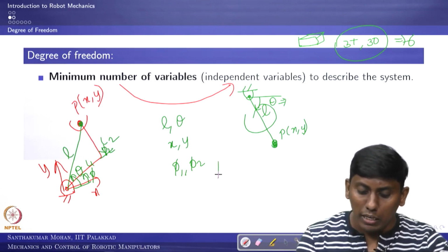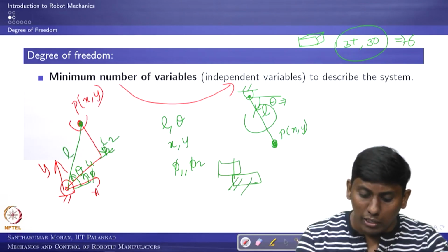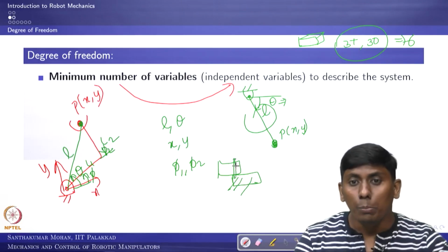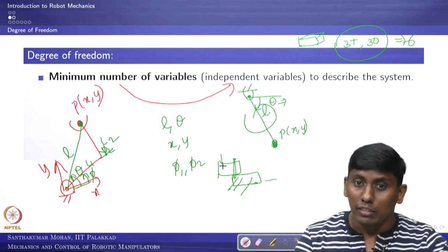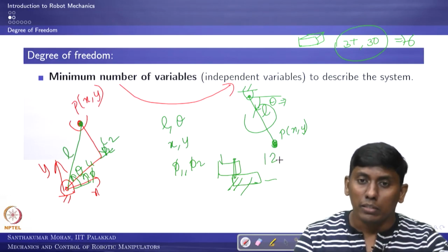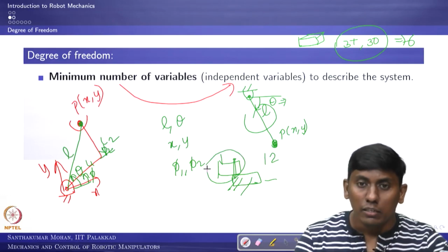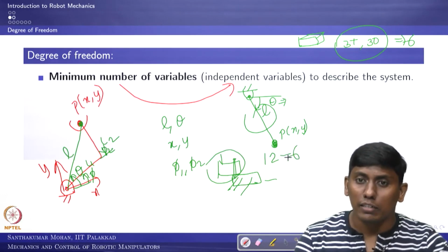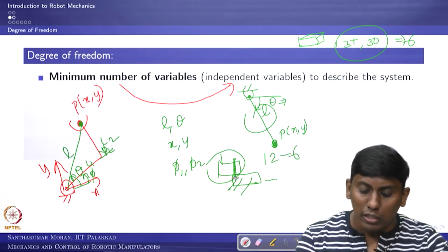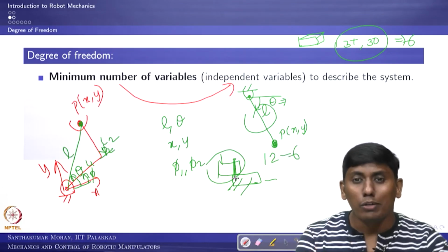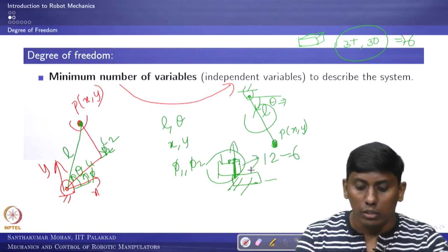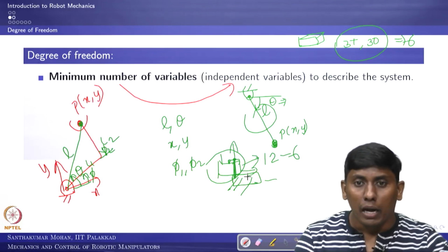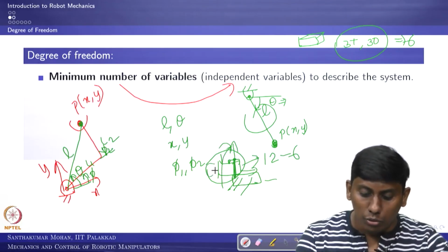Now I am taking one body and constraining it with another body. Okay. This is the ground, and I confine this with a pin joint. So now how many degrees are there? Ground is 1 and this is another one, so there are 2. So 6 plus 6 is 12, but this can move only one body, so another 6 is subtracted. Further, what happened: this particular pin joint will allow only one rotation. It is like a proper collar; it cannot come out, it cannot go out, it cannot go this way, and it cannot rotate this way or rotate independently.